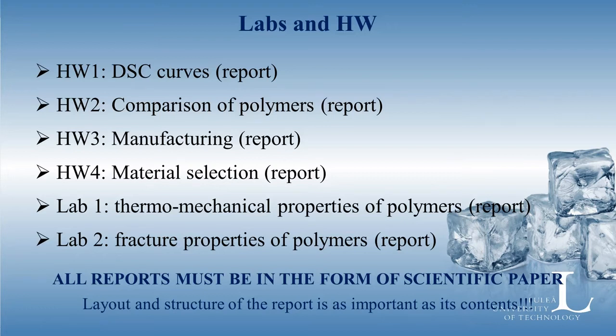So you have processing parameters, and then you have molecular structure, which depends on that, and then you have mechanical or thermal properties, which depend on molecular structure. So we have this chain of events, so to speak, and we should be able to connect processing with the properties. When I say processing, I mean different processing conditions such as, for example, temperature, heating rate, cooling rate, and such. As an example, I can mention that cooling rate will very much affect crystallinity of a polymer, for instance.